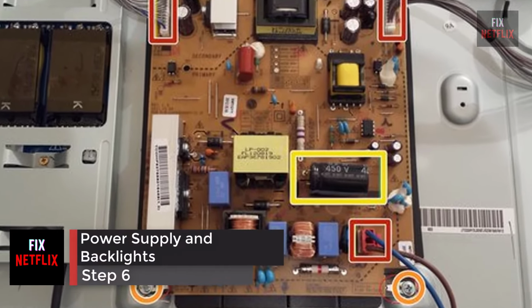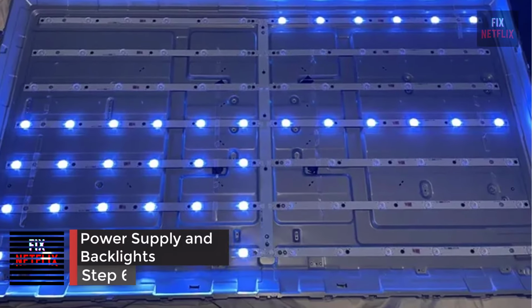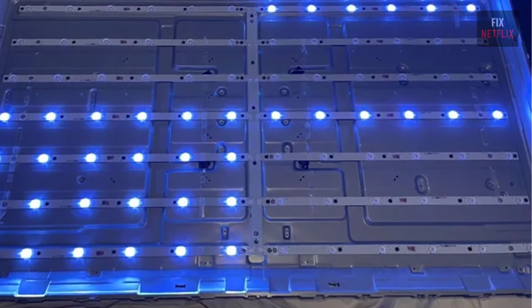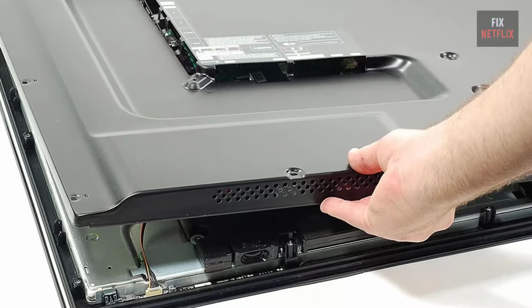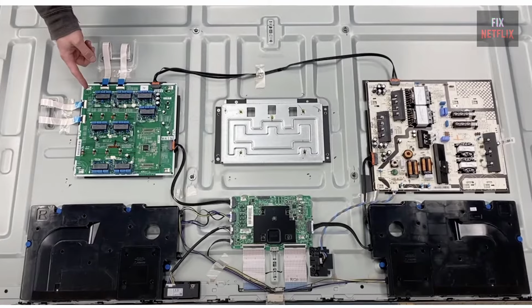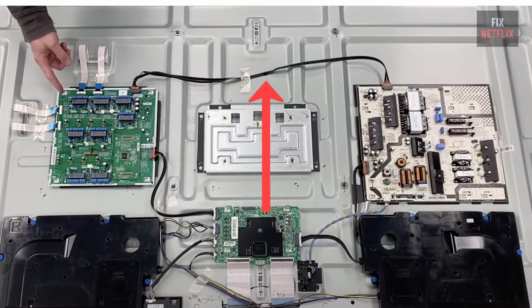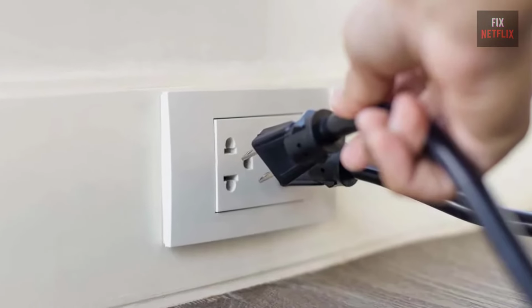Step 6. Power supply and backlights. You can check the power supply and the backlights in one swipe. Make sure the TV is unplugged. Open the back. You may need to remove the base to access all the screws that hold the back on. Disconnect the black cable between the main board and the power supply board. Plug the TV back in.